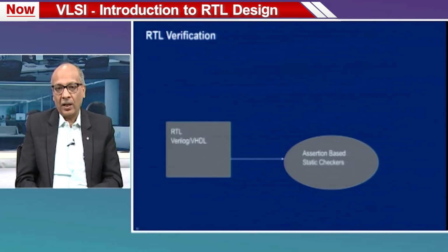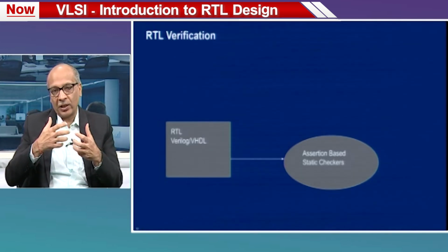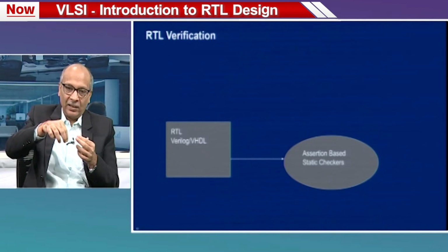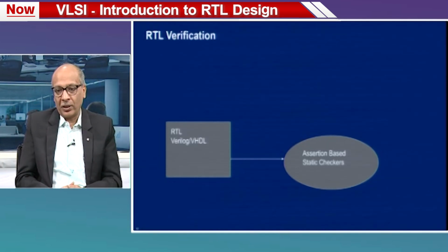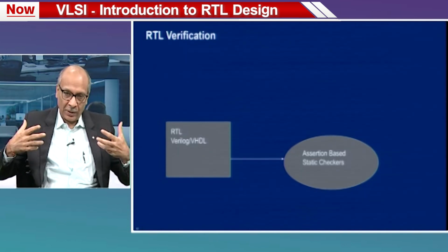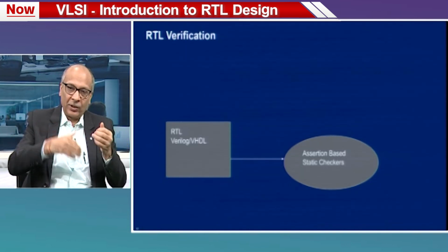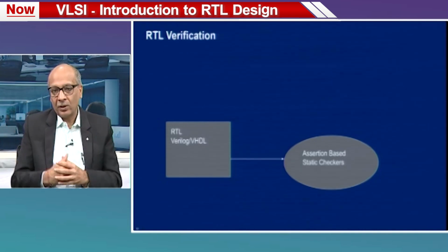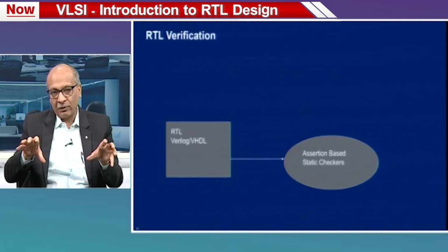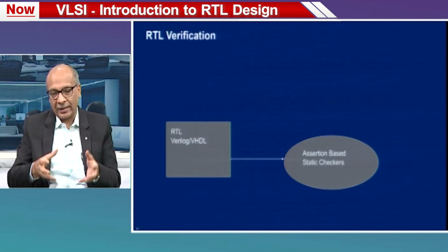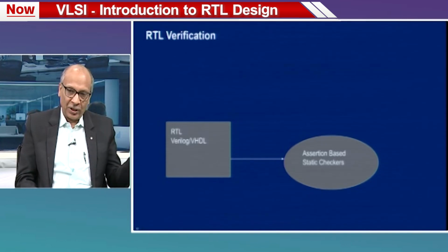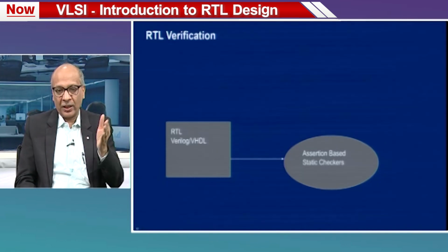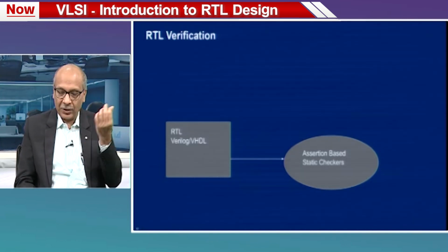And assertion based is, as you are designing your circuit, you might put in your intent, and some assertion tool can check whether that intent is being met or not. For example, again using a counter as an example, you could say after 10 it should give 11, right. So, that is an intent. The assertion checker will check that, given the circuit realized, will it actually give 11 after 10, and so on. So, RTL we verified earlier using simulation. After simulation we would run assertion checkers or static checkers also, and static checkers also means linters.